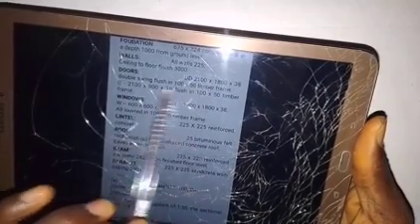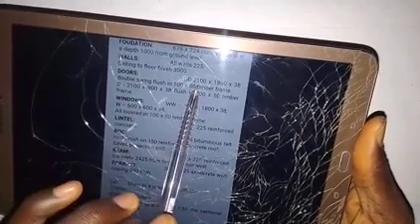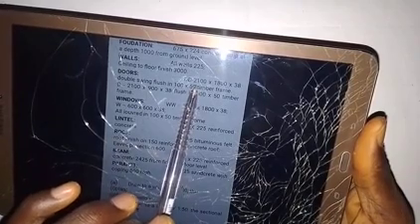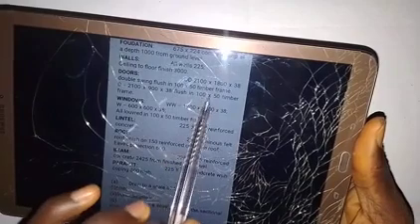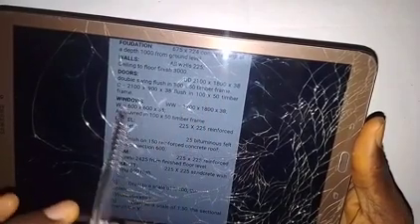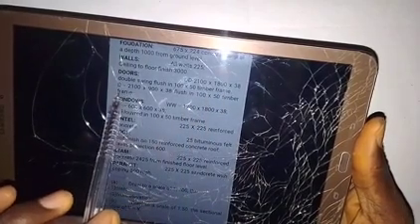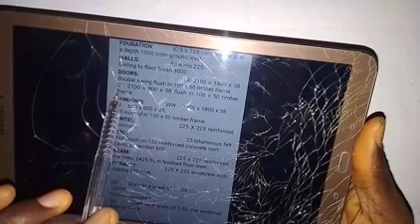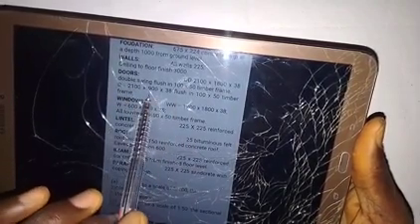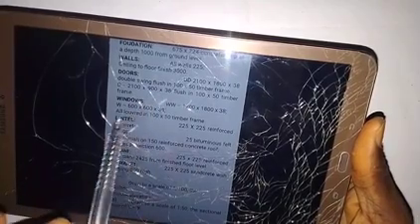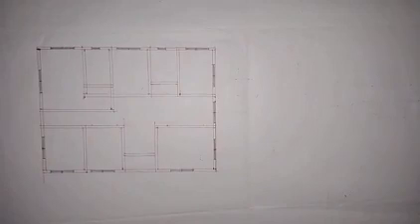For the dimensions of the door, this 2100 is the height, so we are not using it in the plan, but we are using this 1800, which is the width. The same applies to the single door. These are double doors, this is a single door, so the width is 900, and that's what we are using in the plan. So let's see how that is to be done.